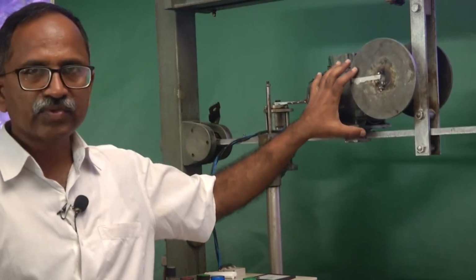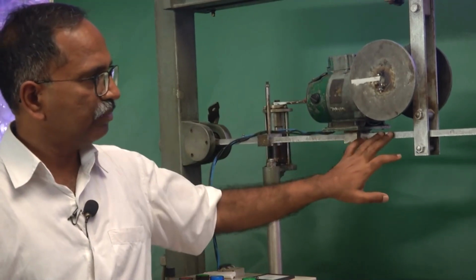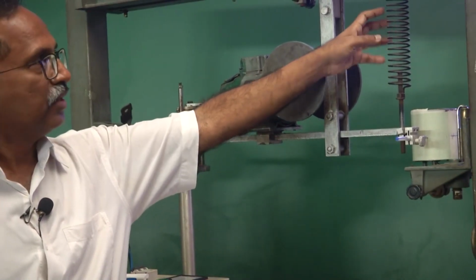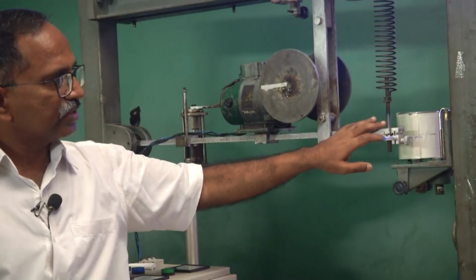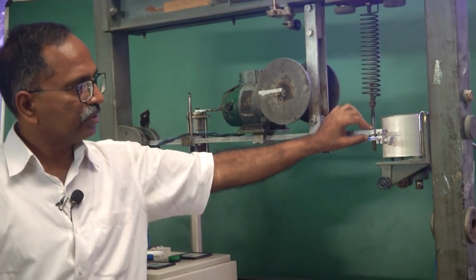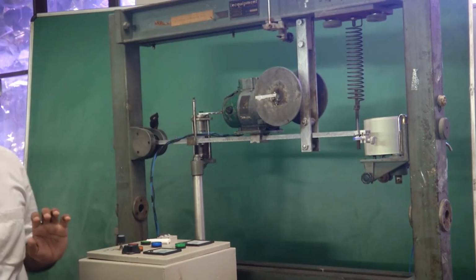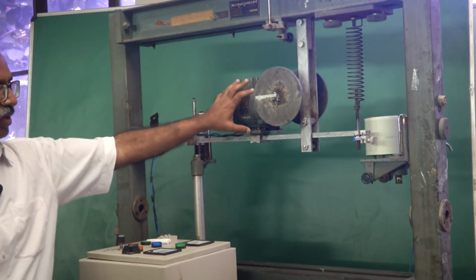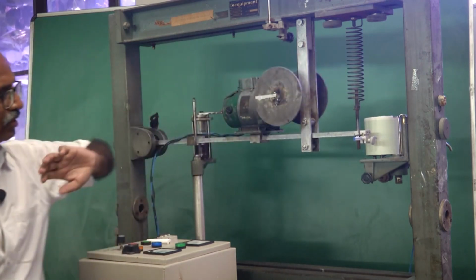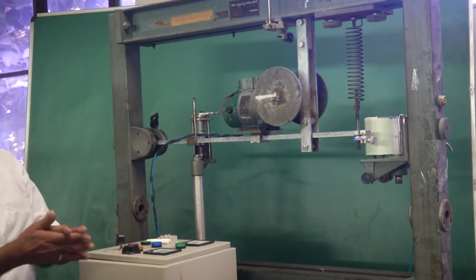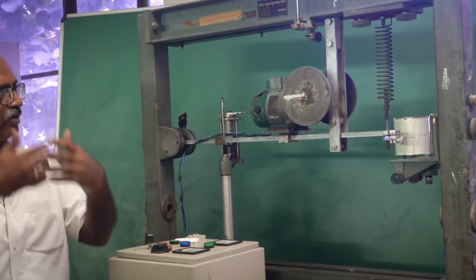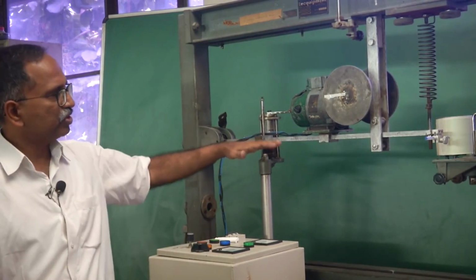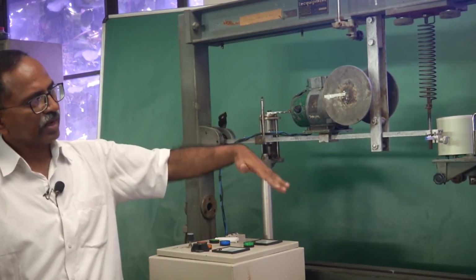Now, apart from this, the mass which is fixed at this location on the beam is hung by a helical coil spring, as you notice here. So, the spring is fixed at this end and it is connected to the tip of the beam at this end. Okay. So, this is the simplest of the vibratory systems, consisting of mass and spring. And unlike a typical spring mass system wherein we have a vertical translatory vibratory motion, this one is an angular vibration. Okay. So, the beam is swinging about this point.